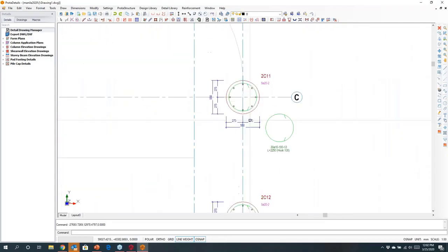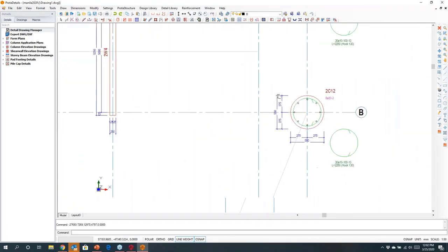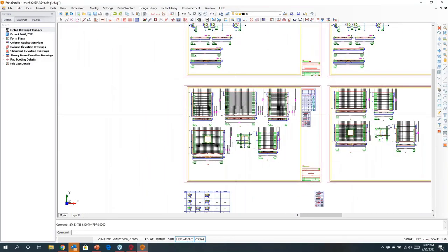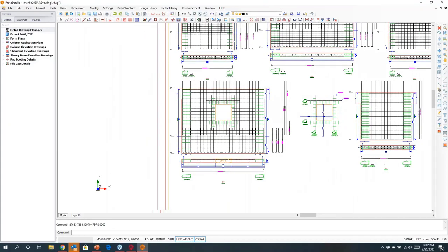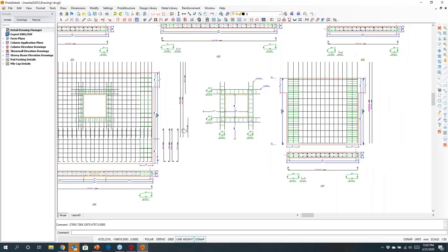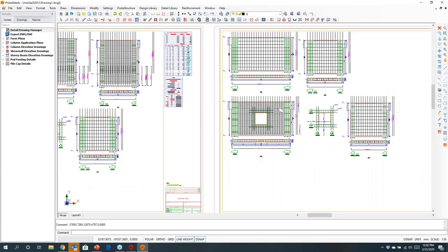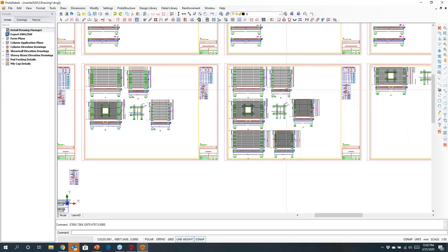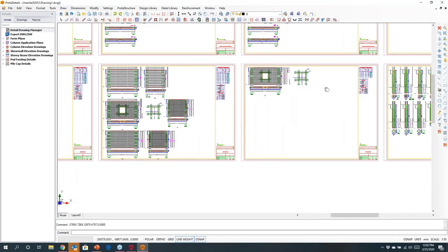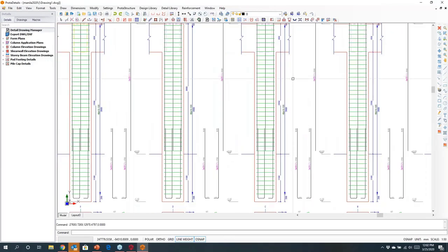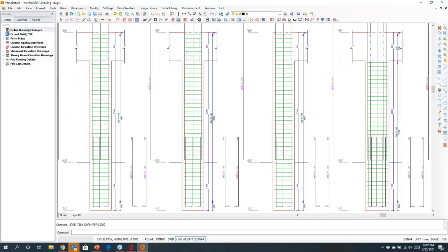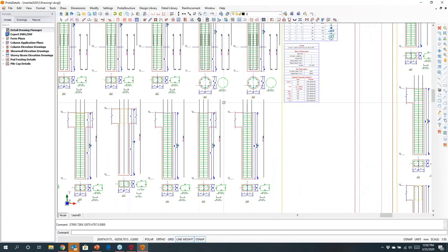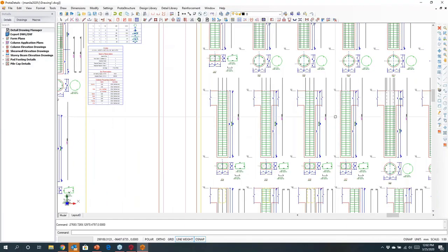You can produce different types of drawings. So if you want, say, set out drawings against grid, okay, you can. But also here you can see other details like our elevations. All these are drawn up here, okay. So for the shear walls and so on, where you've got critical height zones, these will be calculated and detailed accordingly. Okay, and you can just see through here that I've created those. If you look at the columns there, again, you can see the detailing that's being performed for the columns. And we will look at containment detailing, and all of this will be included as part of this.